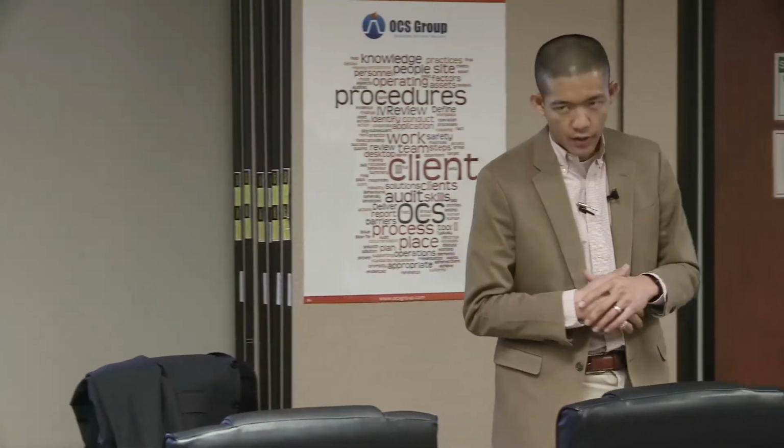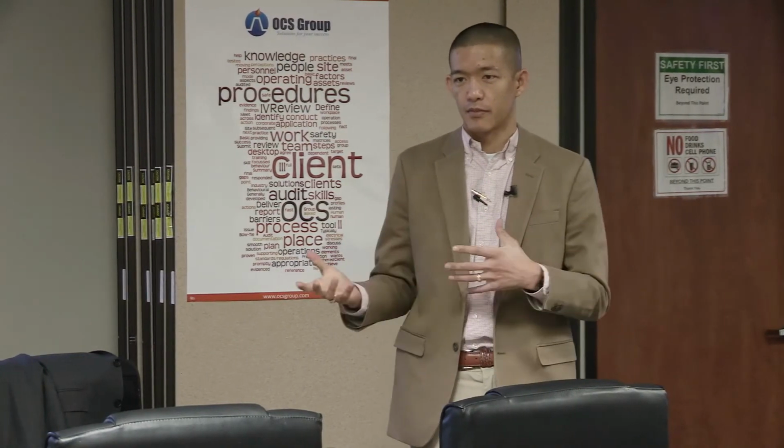Come again? So in MOC, when you make a change, you have other than in-kind changes, where you're making a change exactly with the same piece of equipment, same everything about it. Yes. Well, it depends on the type of specific equipment; it helps to have somebody review it. If you're just changing out a light switch or receptacle, no, because there's really not enough fault current available at those terminals to sustain an arc flash.